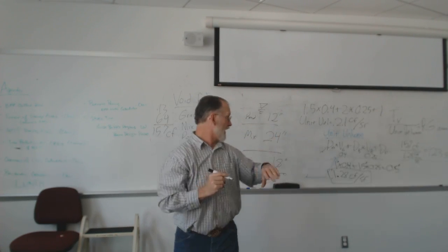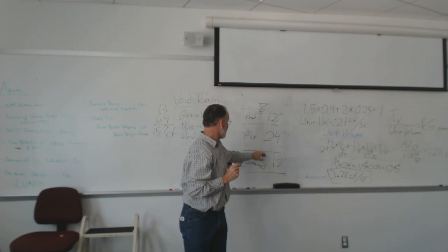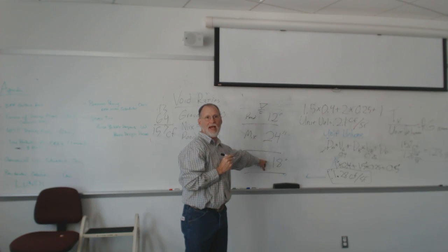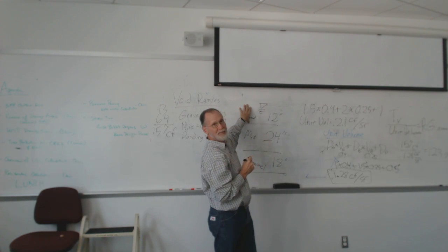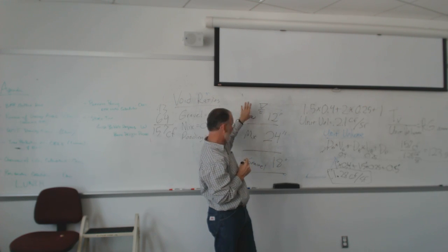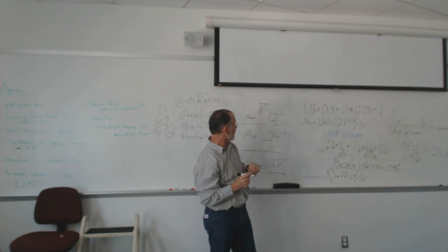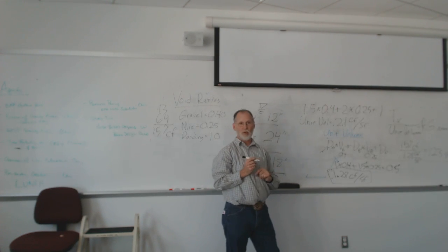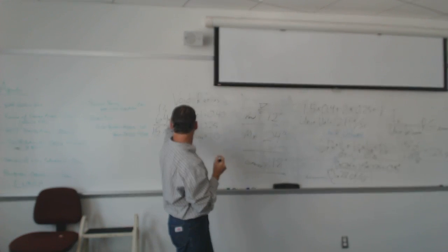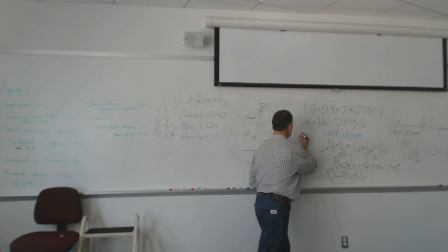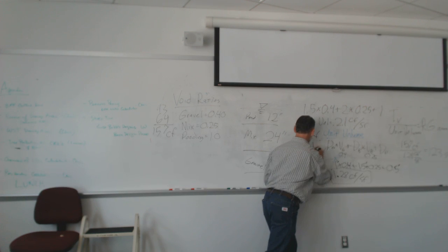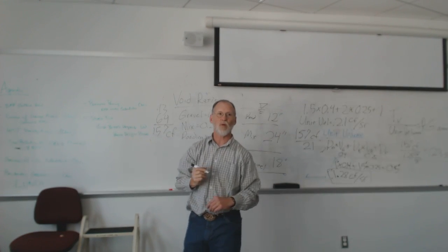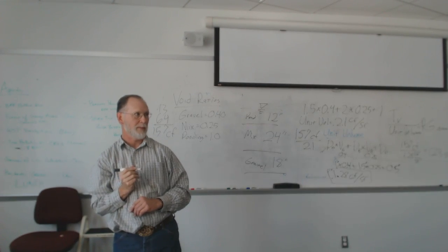Does everybody see where that number came from? We increased our depths, and ponding's the biggest impact. Increasing your ponding depth is huge. Gravel's next biggest, with its big void ratio, and biomix retention is less. But we add them all up, 2.1 cubic feet per square foot. We've got 157 cubic feet to treat, divided by our 2.1. So how much square footage does this one require?